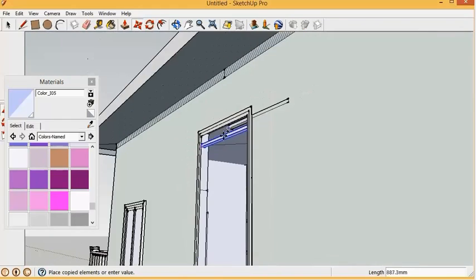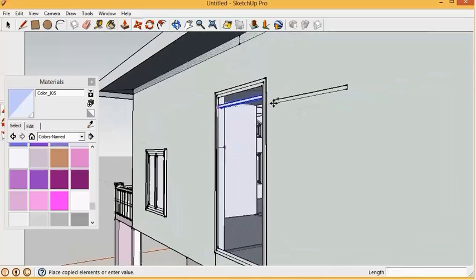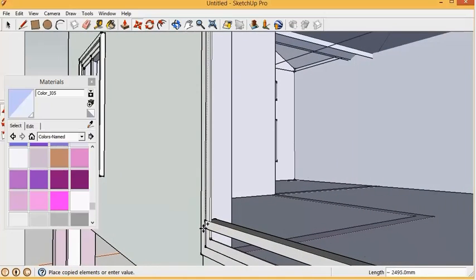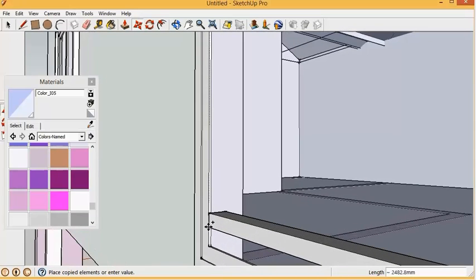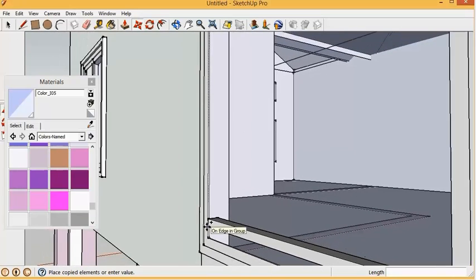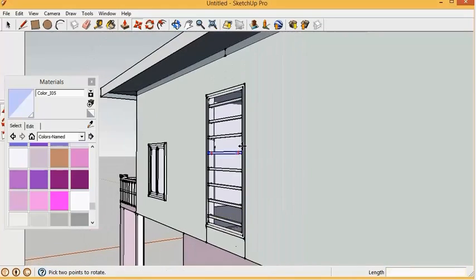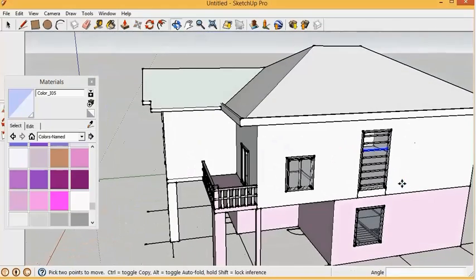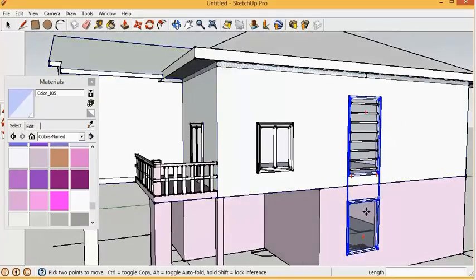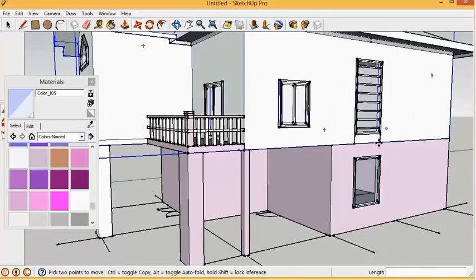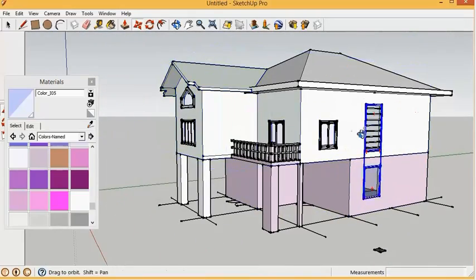And what this does is it brings up basically a little plane, and we can align that to horizontal or vertical surfaces of our object. So let's go ahead and align this to the roof of this building and just left click. And when we do, it creates a section. Now I can left click and drag and select this, highlight it in blue, and then use the move tool to move it up or down. So if I move it down enough, I'm getting basically a floor plan for the building.